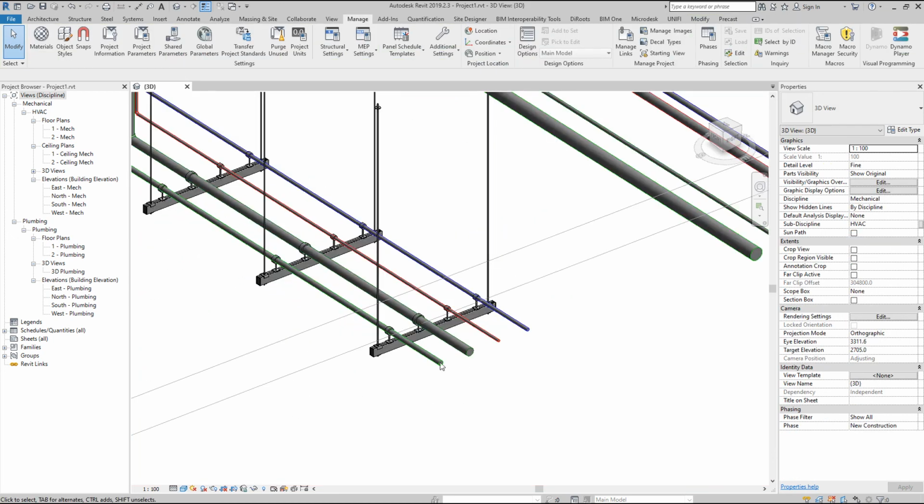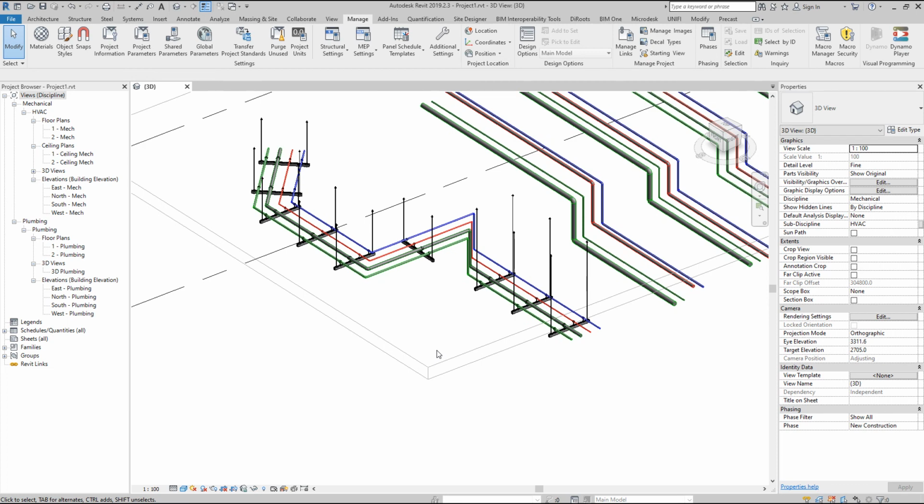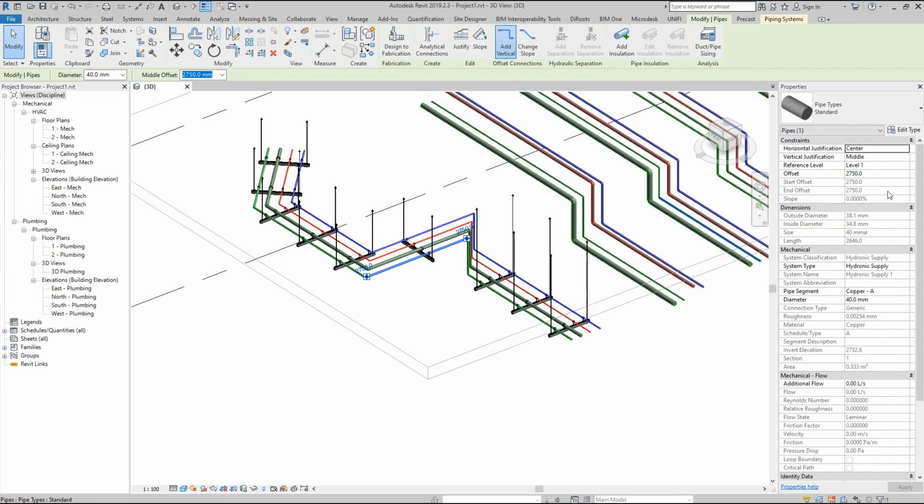And that is all for this script. I hope that you did learn something new. Also, there is a note that I did create this script for Revit 2019, and you know that for 2019, when you're dealing with the pipes and the ducts, and you need to set a height, or you need to read the height, you're dealing with the offset parameter. If you want to use this script for any further version of Revit, then you will need also to change parameter names for the pipes.